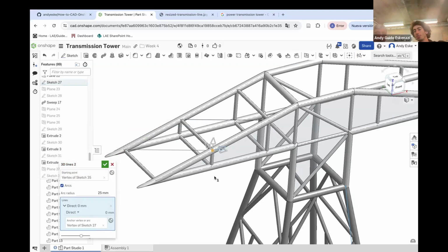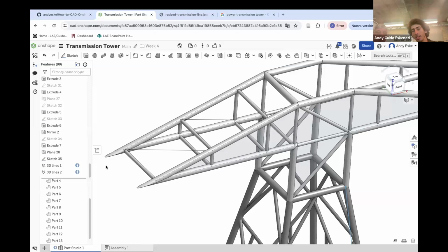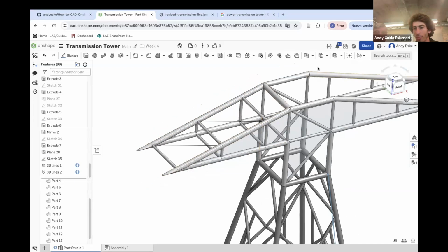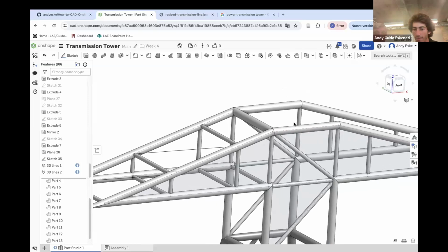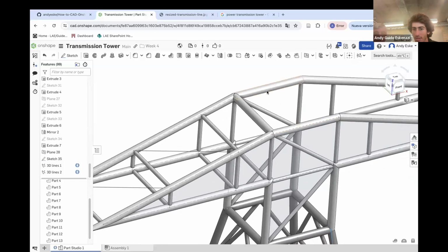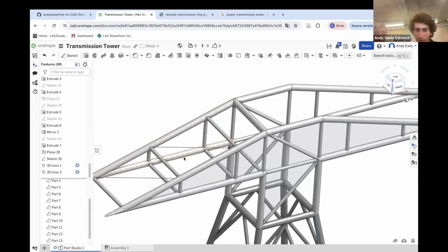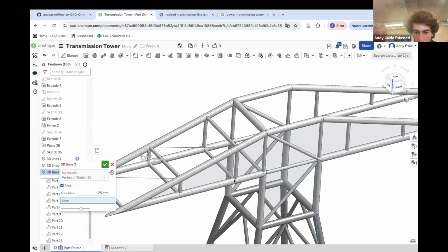This is nice because it's just defined by 2 points in space, right? That's where we're going to do a cylinder that goes there, another cylinder that goes there. Rather than creating a separate plane, you choose this. Okay. It's a little bit quicker because I already have the points, and maybe I'm being too lazy here, but yes, let's create another 3D line that goes between this point and that point.